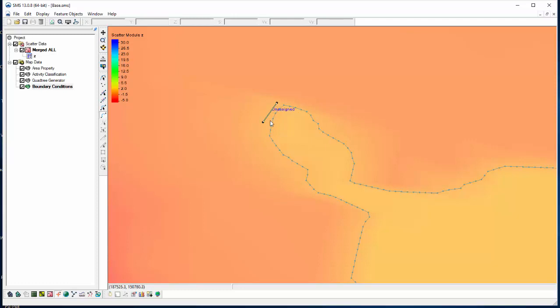And so I will just choose that right there. It needs to be relatively close to the land-water interface. Since it's inside the domain and not on the edge, SMS needs to know where it's going to be. And we can't force it too far back because it really needs to know what cells, where it's defining the land-water, to use. There's a way we can see that later on, and I'll go into that. But for now, let's just keep it as it is.